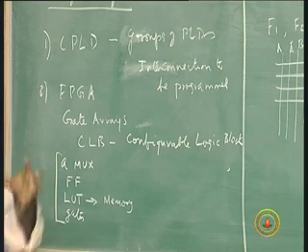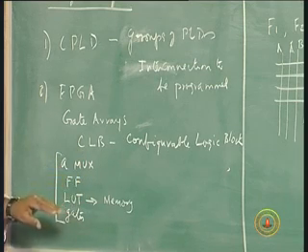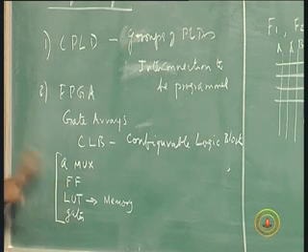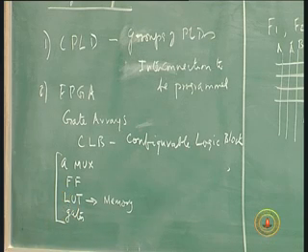And like that, several groups are there, and each of them has the same standard features. Each of them will have a single mux, maybe 4 to 1, a single flip flop, a lookup table of a small size of 8 words, 16 words, and then a few gates, exclusive OR gates and all that. So your whole system requirement of logic has been broken down into these small things.